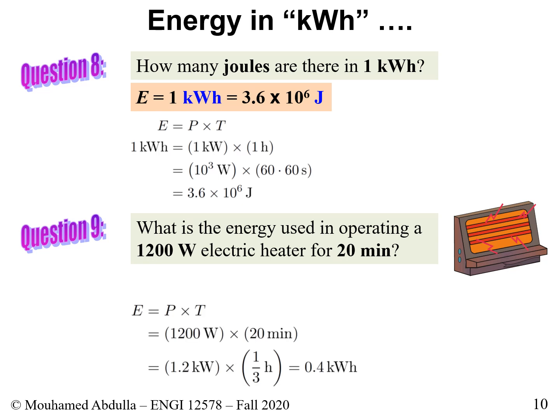So let's go through the motions here. Energy is equal to power times time. Again, we took power equals energy divided by time, and we rearranged it, so it's in this format. The power is 1,200 watts. The time is 20 minutes, so times 20 minutes. Because we want to have the measure in kilowatt hour, we change the 20 minutes to hour. So 20 minutes is essentially 1/3 of an hour, or 0.333 of an hour. Now if I multiply them through, so basically I do 1.2 divided by 3, I end up with 0.4 kilowatt hour, kWh. And this is what we get. So the amount of energy that this heater will consume is 0.4 kilowatt hour.